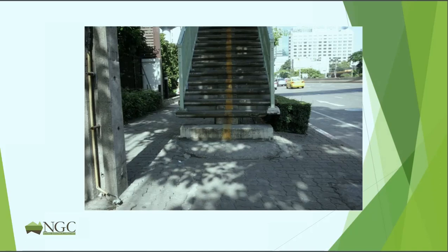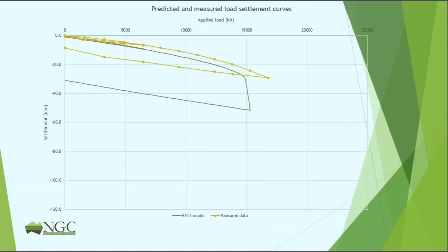It's settling typically about 20 millimeters a year. So the ground surface is continually going down, and a building on deep piles will, like this, not be going down. So we just need to keep that in the back of our minds. We did an instrumented static load test, and I foolishly made a Class A prediction, which is that gray line.